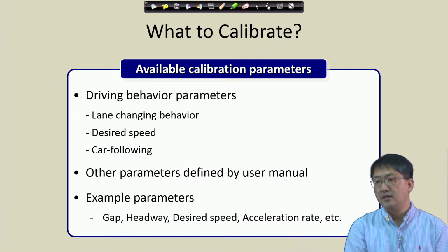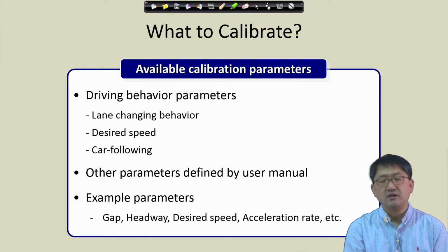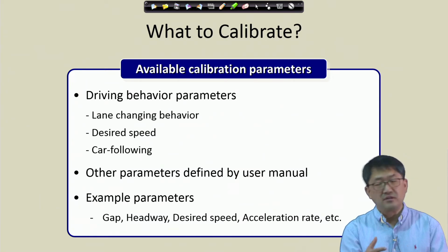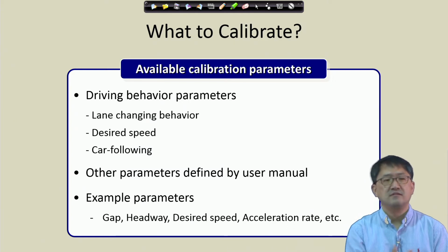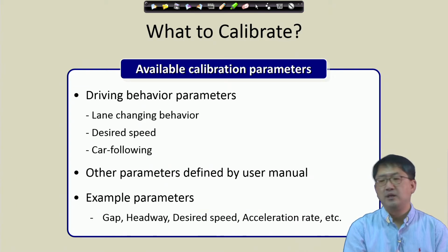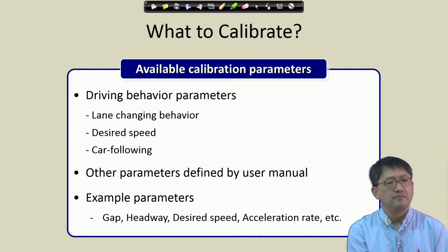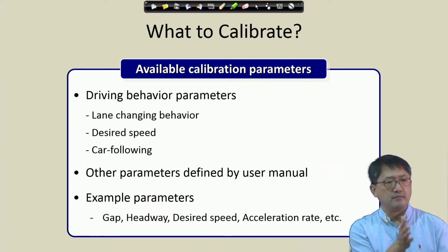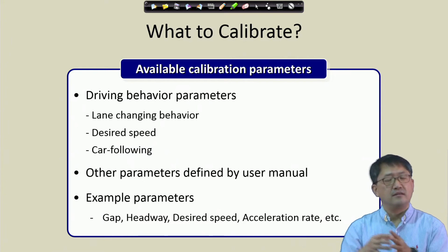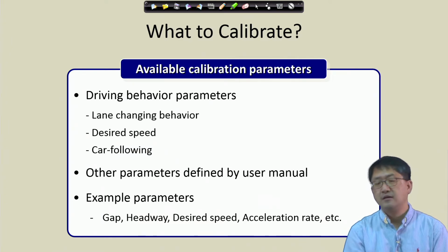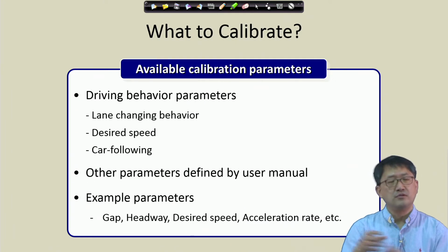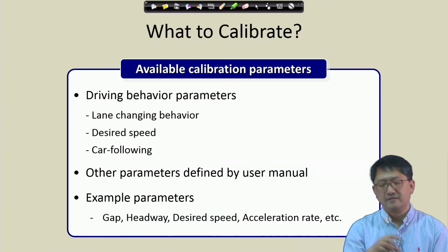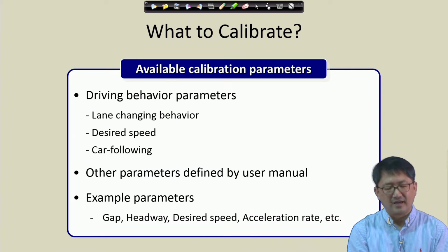Arrival distribution is one of the key challenges. So we can mimic them. Is it random arrival? Is it following Poisson? Is it following platooning arrivals and things like that? And then there are differences, mostly because of drivers' behaviors. You might have heard about the platoon dispersion model, Robertson's platoon dispersion model. That kind of mimics people when they start from the upstream as a platoon of saturated flow, and they usually don't travel like a train. They spread out. This is because some people want to go faster than others. Some people don't want to go fast, and they're creating those fluctuations, and then the proportion of the progression of the cars changes over time.